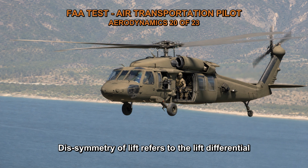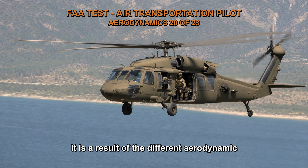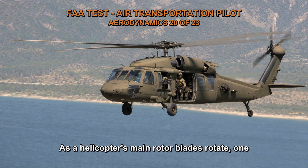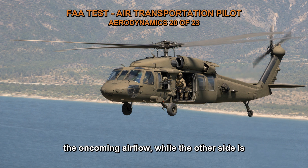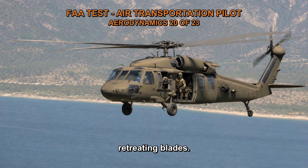Dissymmetry of lift refers to the lift differential that exists between the advancing main rotor blade and the retreating main rotor blade in a helicopter. It is a result of the different aerodynamic forces experienced by the blades as they rotate through the air. As a helicopter's main rotor blades rotate, one side of the rotor disc is advancing into the oncoming airflow, while the other side is retreating and moving away from the airflow. This creates a difference in the relative airspeed and angle of attack between the advancing and retreating blades.